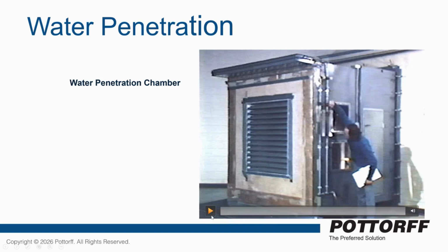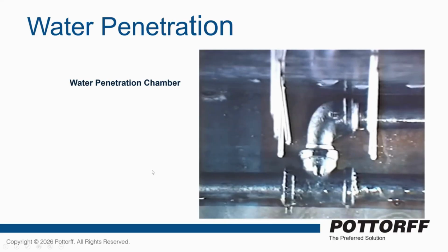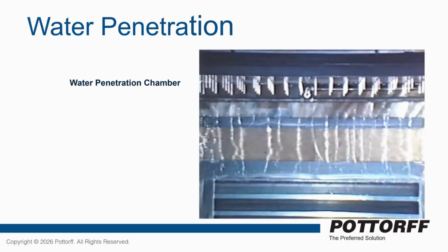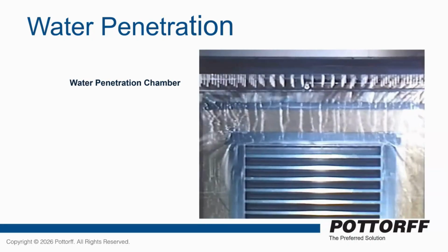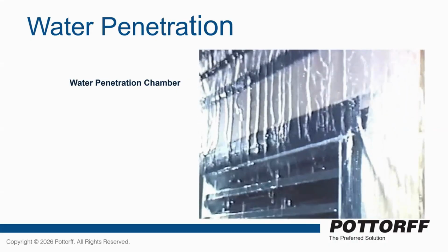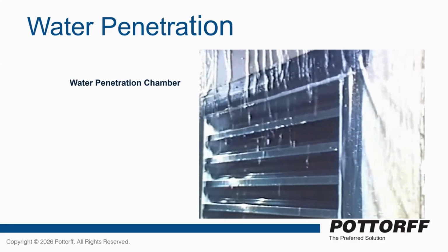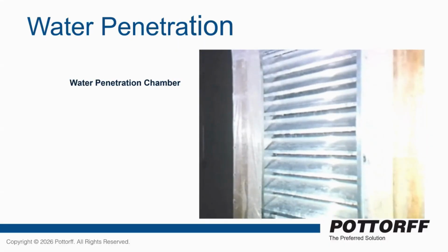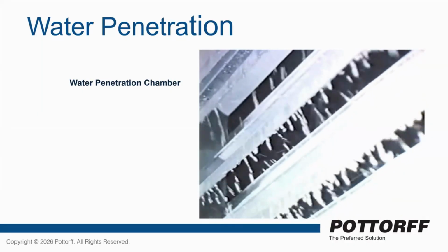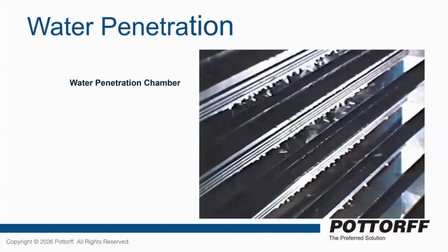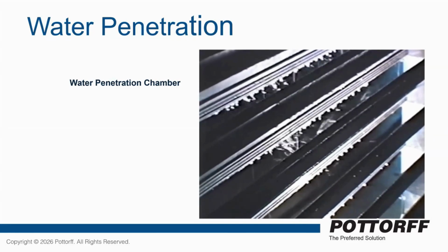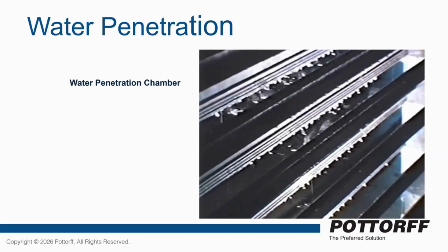It will give a little video here, as you can start to see. This is a bit older video, but the test really hasn't changed too much. You can see water simulated running down a building, and some nozzles at top dripping water. You can see it dripping, and then water running over the face. This is a little bit older louver, but that fan is pulling water in. You can actually see some cascading. Here's the fan on. And this is an interior shot of the louver, so you can see water being pulled in. It's being sucked in right there.